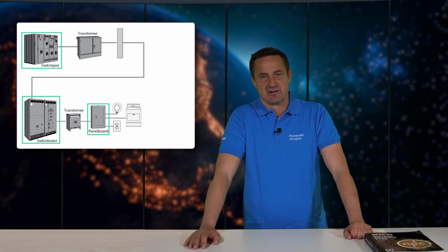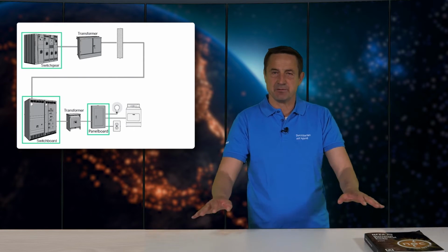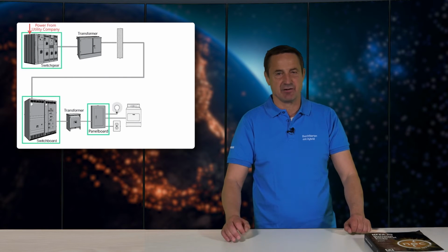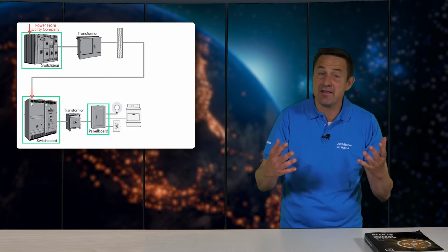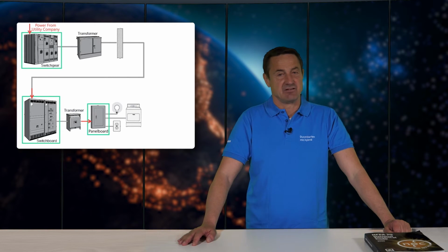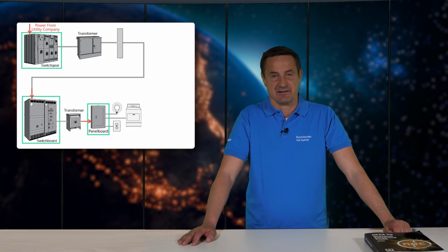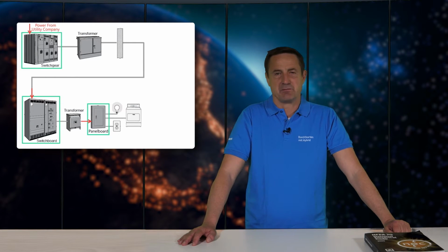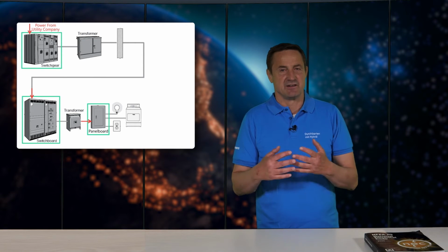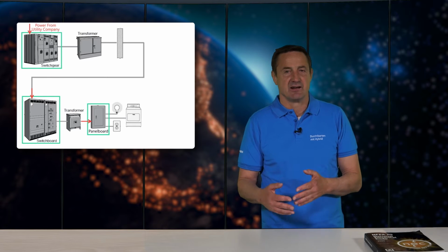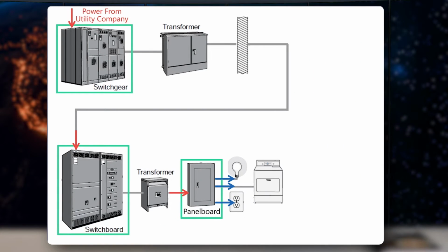These distribution boards are all designed to distribute electrical power in buildings. So the line side of them gets the power directly from the utility energy company or from other distribution boards and transformers in the building. These distribution panels supply low voltage loads which are typically installed in buildings, like lighting, heaters, receptacles and air conditioners.